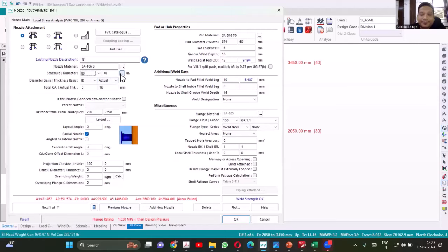If yes, then I'll go back to pipe and we'll try to complete the data for the rest of it. So when I'm selecting pipe, I'll be selecting OD, and I'll be selecting the minimum thickness. Okay, 80 is not getting qualified. So 80 thickness is sufficient, and only area is not getting qualified, so I can take care of that. I can have a 100 mm RF pad. Now that area is getting qualified. I'll come to that.